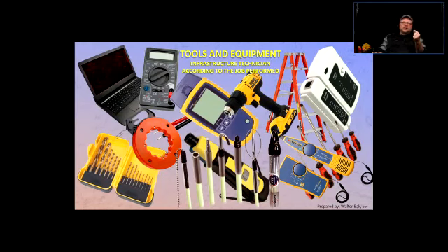So you get the connector that's coming out of the tone generator, you clip it directly onto the pair that you're using, and that is going to introduce a tone. With some of them, you can switch from a continuous tone that's going to sound like beep, quite annoying, and you can also switch to an alternate frequency tone like dee dee dee dee dee dee dee dee, much better to notice.